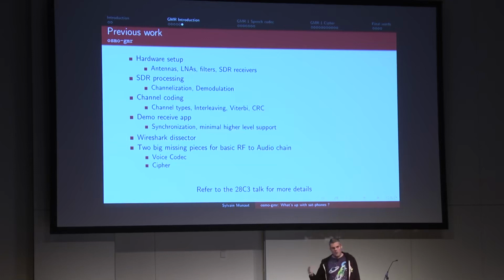Then we did all the SDR processing, which is taking that raw data, filtering it, selecting the channel, doing the demodulation, getting actual data bits out of it. Then channel coding, which is converting those data bits into layer 2 frames. Then interpreting those layer 2 frames into channel assignment and following those assignments into a demonstration application. And finally, the Wireshark dissector, which takes all of this and presents it nicely in a way you can actually read.